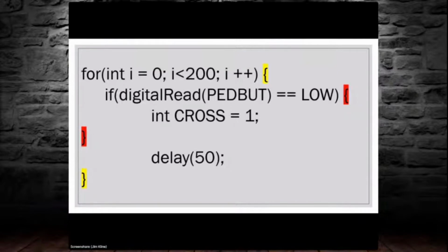In order to reset for the next cycle, the sketch will need to clear the variable cross by placing a numeric value that is a non-1. This should be done in the area of the code that you will be modifying to implement a time delay for pedestrians to cross when both the north and south, east, west faces are red, which is during the delayed green cycle. In this case, I would suggest writing the code to place a 0 in cross once the code is active in the delayed green portion.